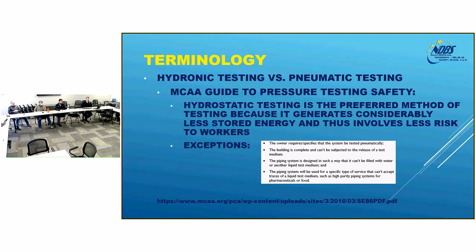I wanted to just mention that I'm not going to talk a lot about pneumatic testing. We do a lot of it here. MCAA, the Mechanical Contractors Association, has taken a position. They've written a position letter on pneumatic testing, and I've quoted it here. Hydrostatic testing is always a preferred method of testing because it generates considerably less stored energy. But they do list some exceptions there that will allow for pneumatic testing.